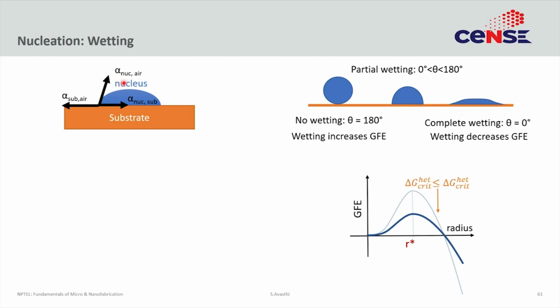And under equilibrium, all these three things balance, and they balance at a certain angle which is called theta, the contact angle, and at that contact angle these three forces balance, and that is what decides the shape of the nucleus, right.